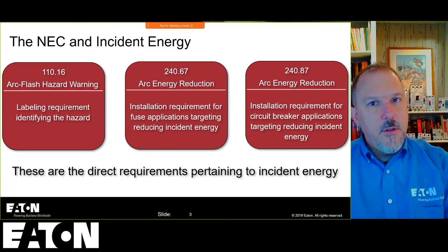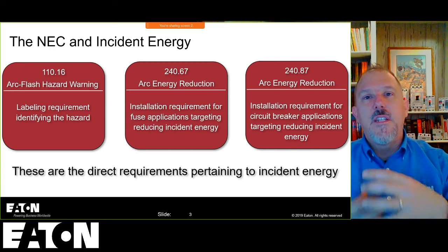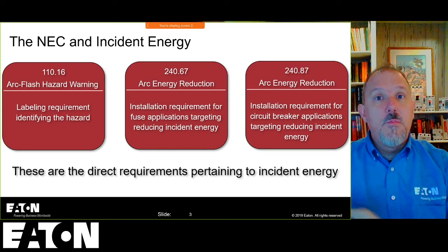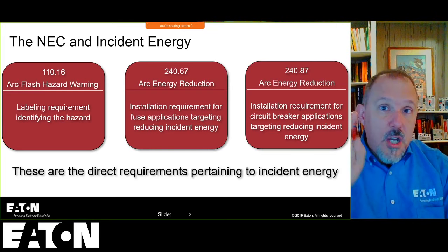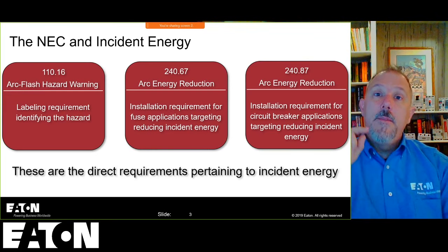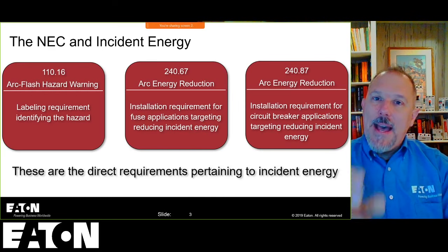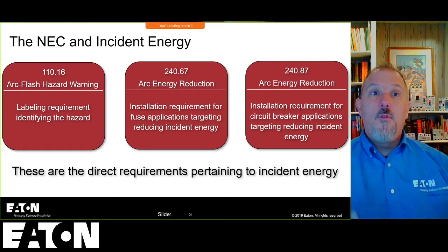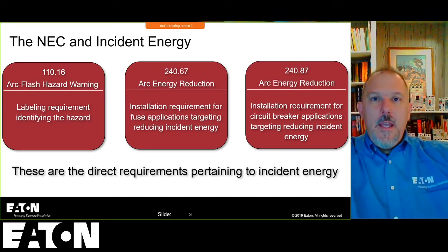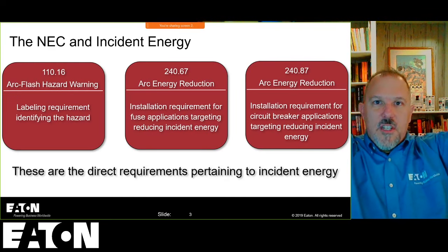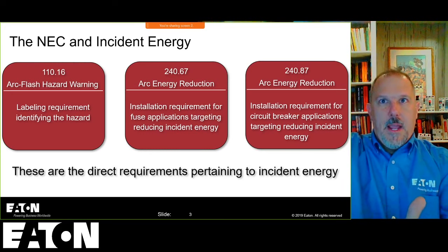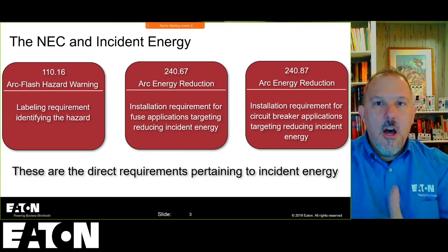You increase the voltage, and then we went from an average of a 600 amp service to a 4,000 amp service. And what that did was move the instantaneous further to the right, and we're going to talk about what that does to us. And you have added delays because back in that day, they didn't have electronic trip units. You had these big thermal mag breakers. I call them the big beer gut, right? Well, if you look at that trip curve, the thermal side of that overload region had a real big error band, and that caused a lot of incident energy.